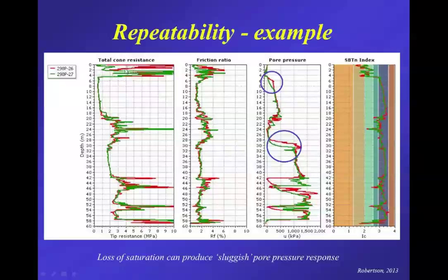Again, you've got about 4 meters of stiff, often fill to get through, then essentially normally to lightly over-consolidated clay, locally referred to as young bay mud, and then a sandier zone, and then into old bay muds, and again, a sandier zone.